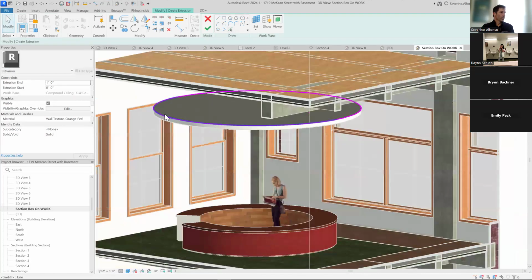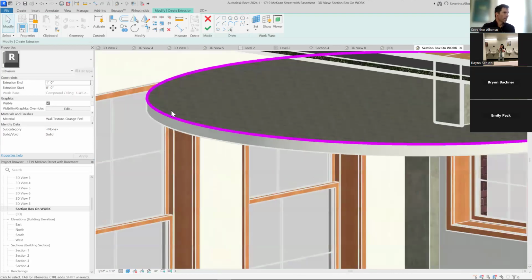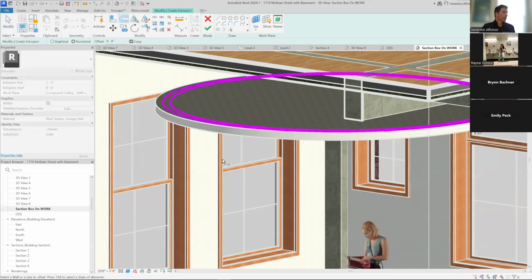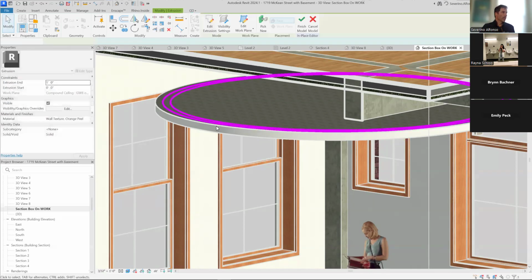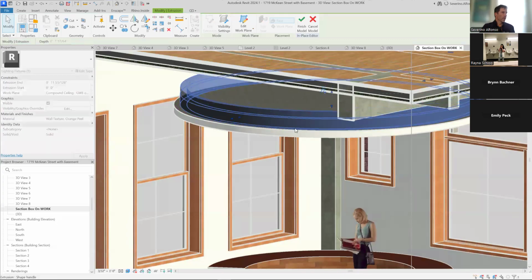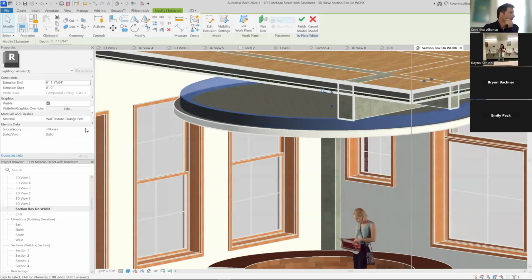And then I'm going to do an offset because I don't want the lighting to start exactly at the edge, just a little bit inwards. So I'm going to do offset. And I'm going to press tab to select the entire circle and delete this one and do another offset. So now I can say, okay, the bigger it is, the more light you have. The important thing is that you can create a form that you can then assign a particular material, and that will be under material.